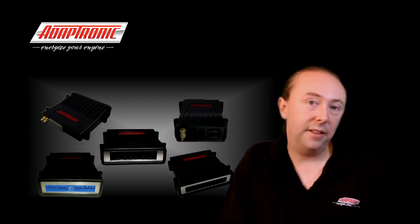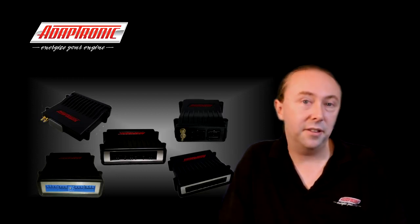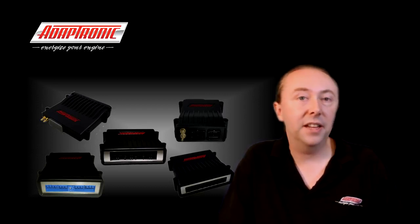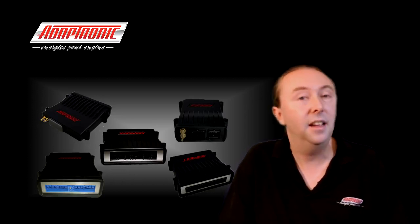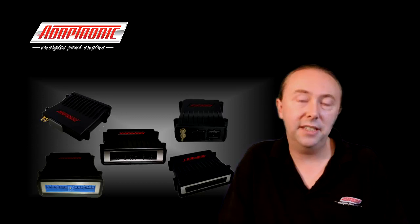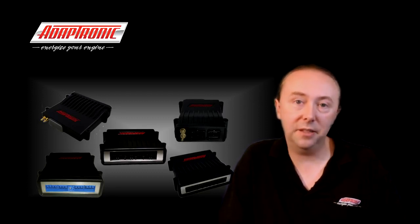On plug and play ECUs that we do for vehicles where the injectors are hot all the time, then you'll notice on those cars that there's a separate power feed for the injectors for the ECU to recirculate the current back into, and that's what we use for that situation, so that one's okay. It's just the wire in ECUs where you need to be careful about this. This injector flyback voltage pin is also shown on the outputs page, not because you can change any settings relating to it, but as a reminder of which pin it actually connects to on the ECU.